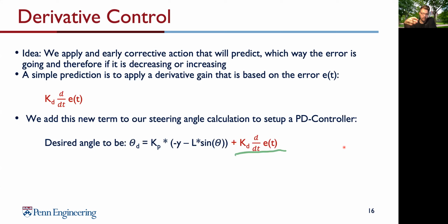So this is better than our normal P controller, but in addition, we have disadvantages here. If you have a systematic bias, like a broken steering that creates a steering drift, it will cause a new and big cross-track error, and we will not achieve reaching the center line.